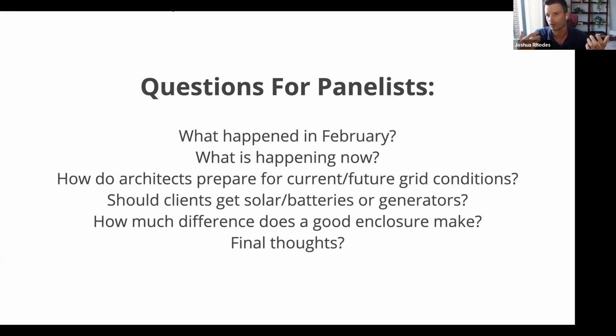I was one of the unfortunate ones who was in the dark for 4 days straight. The blackouts were supposed to roll. Obviously they didn't for many people. The reason given was that for rolling blackouts, you have to turn one feeder off before you can turn another feeder on. And there was so much critical load that they have to keep on, think hospitals, fire, EMS, things like that, that they were not able to turn off any more circuits in order to turn others on. So they just could not roll that usage around, and you ended up with people with it close to freezing or freezing inside of their homes.